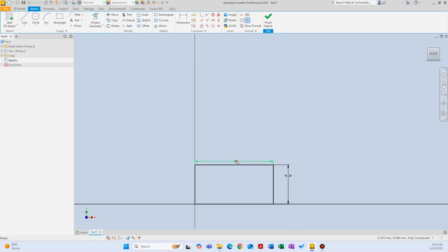Also, I can just come here in this edit dimension text box, and I can use, for example, I can call this length. I can type length, and then hit space, equal, space. I didn't even have to hit space. I could have just done this. Now I assigned a name for this. Now the 60 millimeter is my length. I didn't want to call it D0 or something. I wanted to call it length. So I'm just going to click OK.